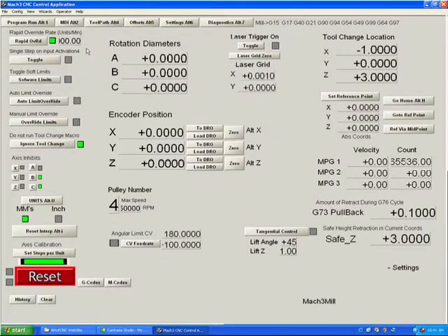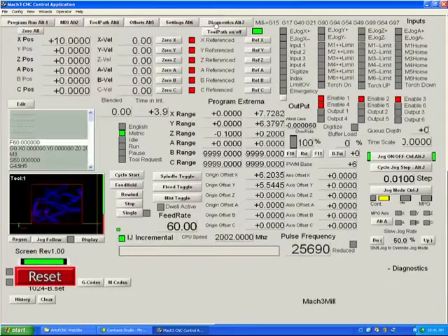We can set a rapid override, which slows down or speeds up our rapids. We can tell the system that when input number 4 is coming into the printer port, to do a single step whenever it sees it toggle. Various settings, and you should need to use none of these as a beginning user. These were all fairly advanced settings and really aren't necessary for most people.